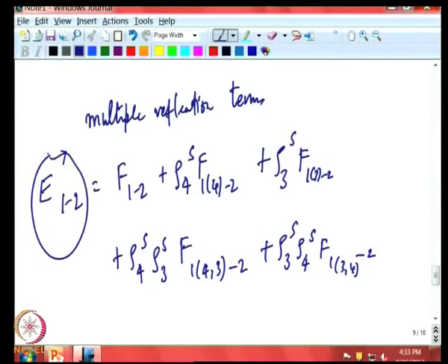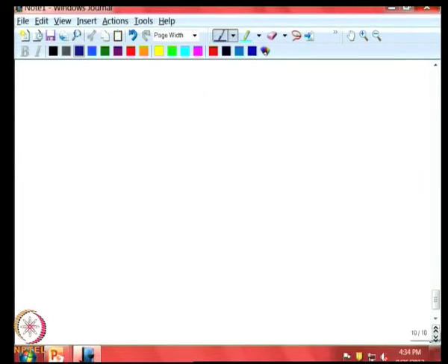Now, just to complete our discussion here, assuming that such new shape factors are calculated, these new shape factors depend both on the Oppenheim shape factor for diffuse surfaces, and all these terms involving specular reflection. So, this is not anymore a purely geometry factor, it is geometry as well as the specular reflectivity of the surfaces. So, let us say we get all the Aij's, how do we do the general problem?